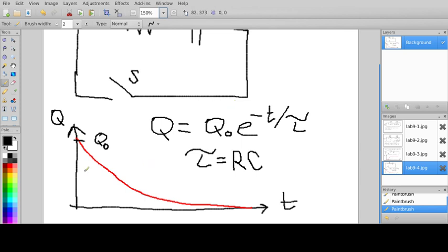All right, so now you kind of understand why you get this red line in here, and you say, well, can we do a more rigorous mathematical derivation of that? You can. I won't even do it in the class. But basically what you get is exponential decay. This is what exponential decay looks like. The charge at any given time, so Q here is actually a function of time, is basically this graph here, and it's going to equal Q naught, which is the original charge, the charge at t equals 0, multiplied by this exponential.